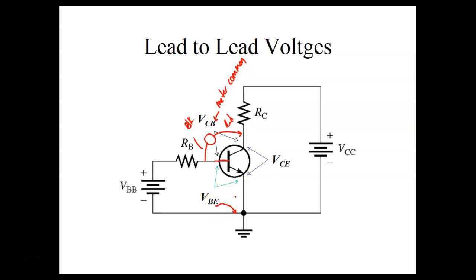Over here I would put my black lead somewhere on the common. I don't even have to get that one on the lead. I can just put that on a common that's all over my circuit, right? And of course over here, if I wanted to measure this, then I could go from circuit common up to this resistor right here. Or if we got a resistor down there. Eventually we're going to put a resistor down there and we'll talk about why.